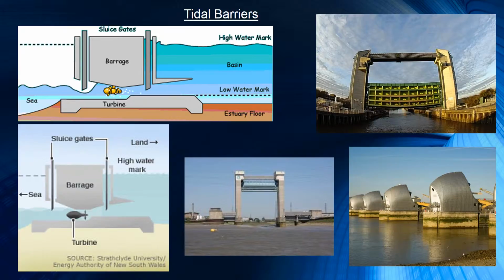Okay, so what kind of ways can you obtain energy from a tidal barrage? Well, there's the ebb generation of electricity. The basin is filled through the sluices until high tide. Then the sluice gates are closed. At this stage, they may be pumping to raise the level of the water further. The turbine gates are closed until the sea level falls to create sufficient head across the barrage, and then they are opened so the turbines generate until the head is again low.